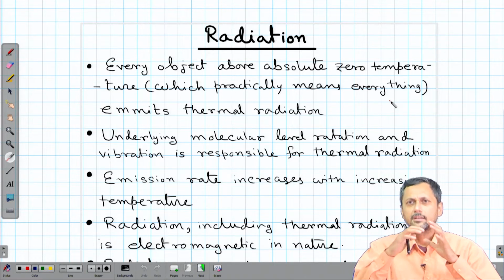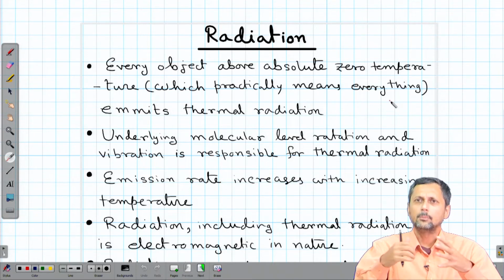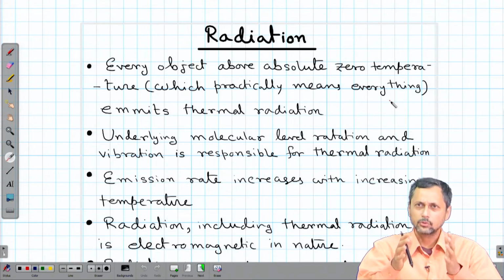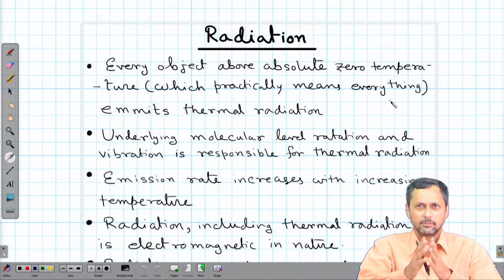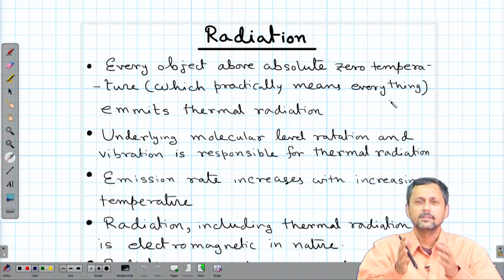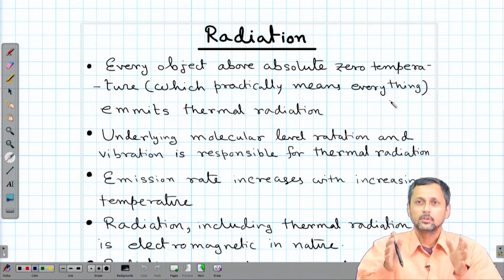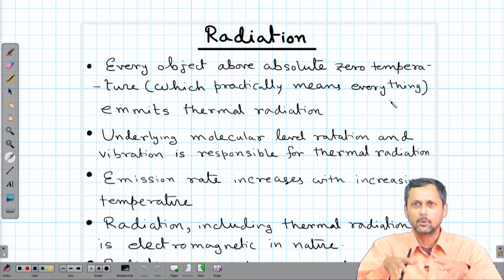Thermal radiation is a certain amount of energy that gets released from the surface of any object, and the underlying source of this energy is molecular level rotation and vibration. For solids, we can realize that there should be only vibration, there is no rotation, but for liquid and gas it could be vibration and rotation both. So, the energy is emitted from the surface, but the source of energy is inside the object itself. So, it is there for the entire volume.